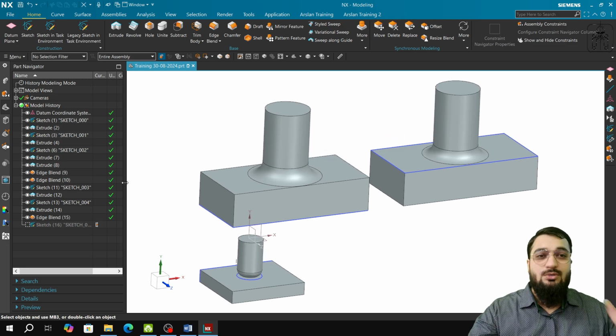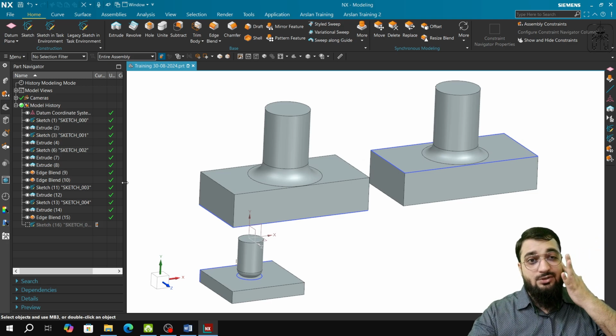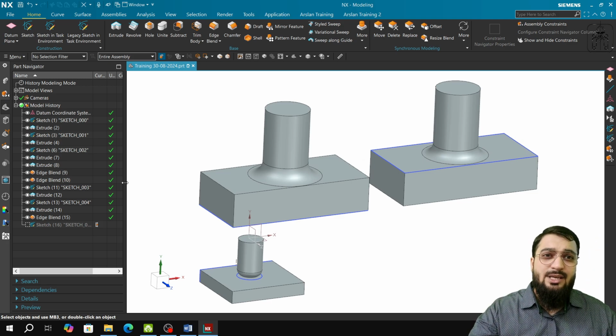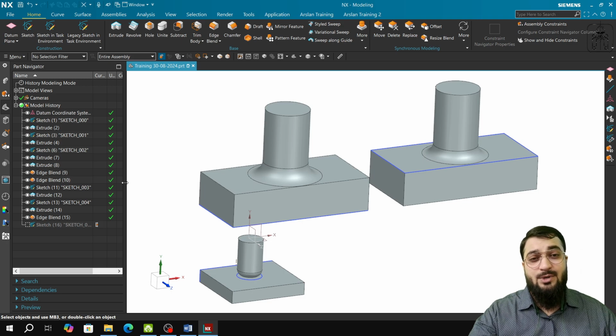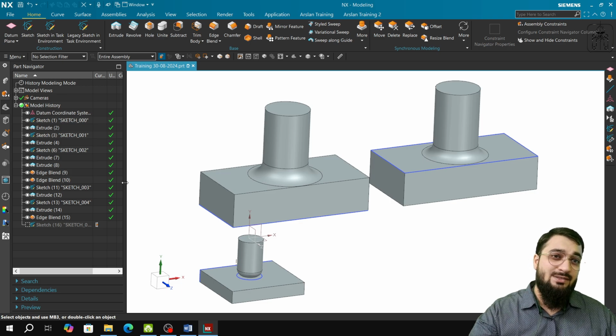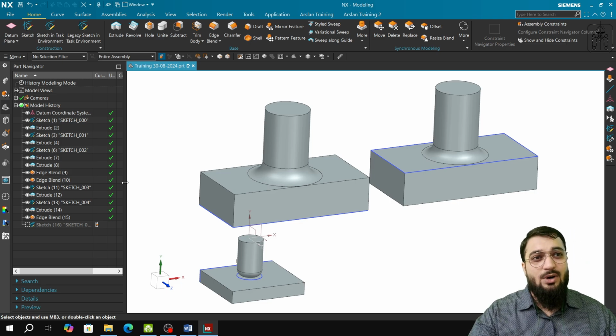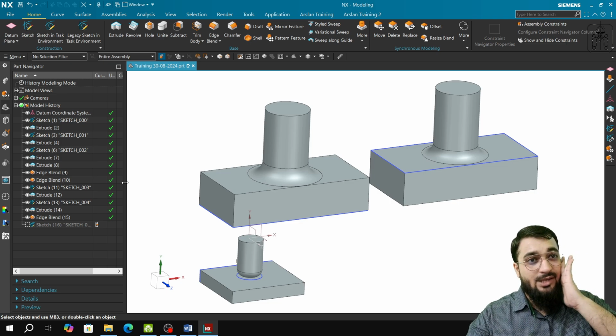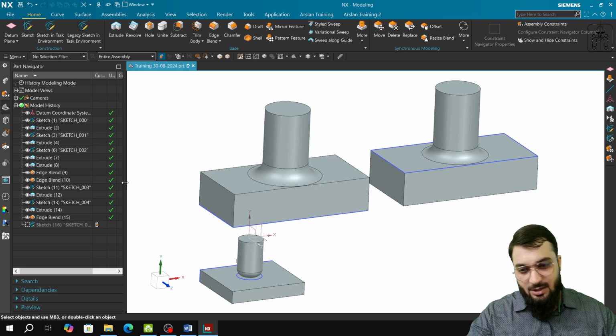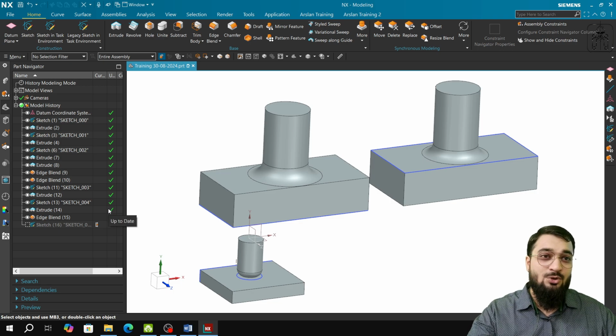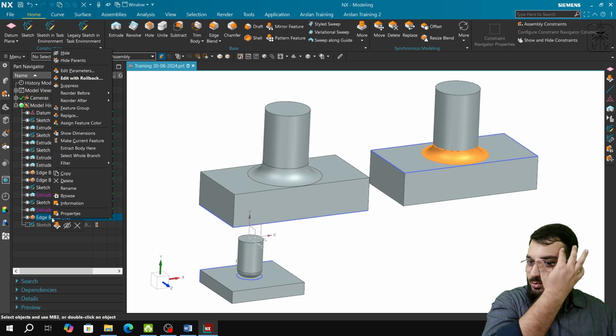So we got to know three things primarily. First is hide and show. Thing which is related to that is show and hide of parents. Second thing is suppressing of a feature, and how suppressing of a feature that is the end result affects the parent, and how unsuppressing the final makes the parent also visible. Third thing is delete, and if anything goes wrong, you can always go for Control Z. So these are the three things which have been done.